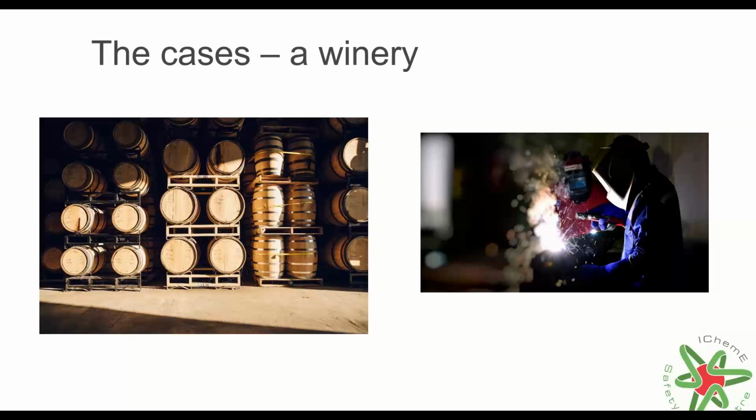And in this instance as well, there was no permit to work system, there was no effective isolation system, and there was no vapor monitoring or gas monitoring to determine whether there was a flammable atmosphere at all present. So they were the two cases that we talked about.